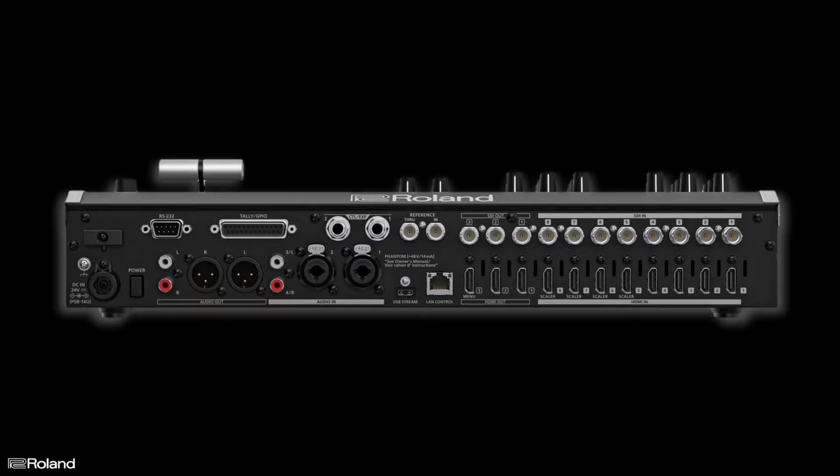If you're outputting 1080p at 59.94 frames a second, you can bring in different frame rates to the SDI and HDMI inputs. As far as resolution and scan type, if you're outputting 1080p, you can bring in a mix of 1080i and 1080p. If you're working with 1080i output, the same also applies. If you're doing 720 output, the SDI inputs and the first 4 HDMI inputs need to be 720p. But those 4 scalers on HDMI 5 through 8 will up or down convert. You can resize and reposition the video in the frame.